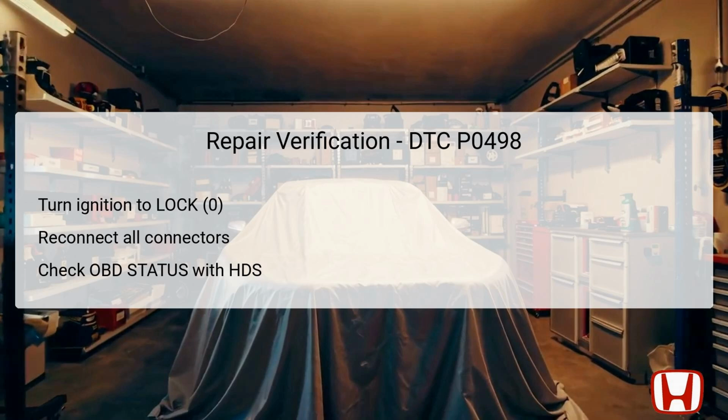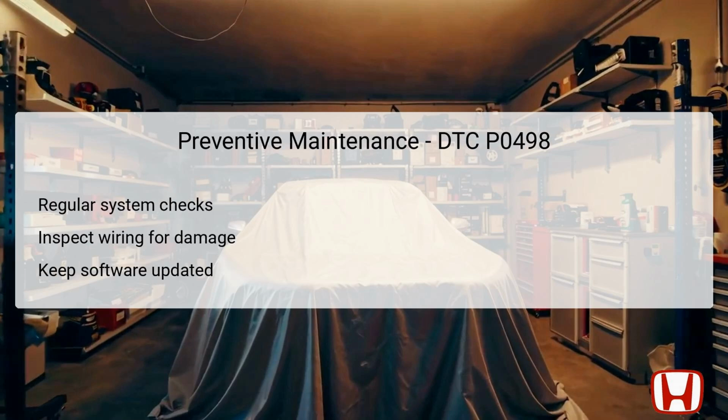If the status indicates passed, the troubleshooting process is completed successfully. However, should it show failed, additional checks are required to diagnose any remaining issues or errors. To prevent the recurrence of DTC P0498, regular maintenance checks on the EVAP system are highly recommended. Conduct frequent inspections of the wiring and connectors related to the EVAP canister vent shut valve for signs of wear, damage, or corrosion to ensure a reliable connection.